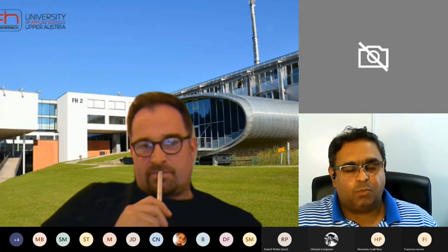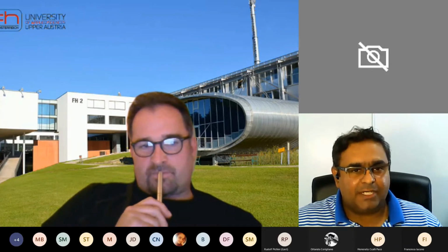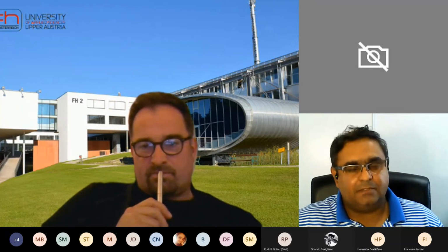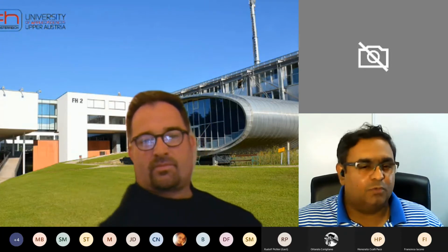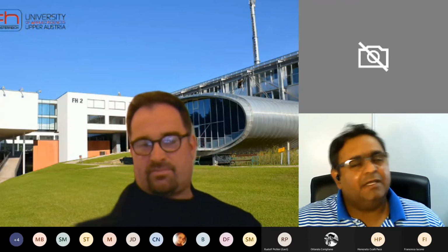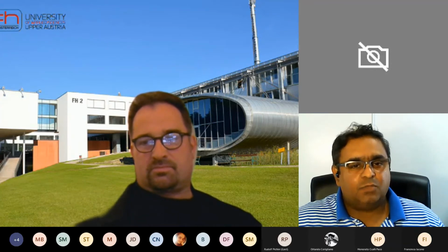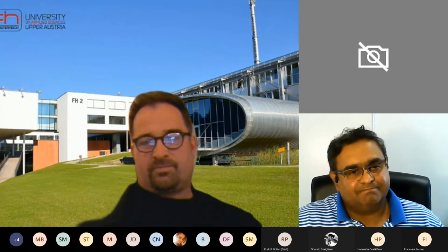Combined the parts into one major part, upper structure and the lower structure. So basically, there were 2 major parts, and from those parts, we just calculated the forces exerting on the mat. If you go about the stability of the crane, that will take much more time, because then you have to check the bending of the beam and the bending of the boom, dynamic loading, everything. That will be so extensive. To save time, because our main concern was how accurate we are in developing a new method.